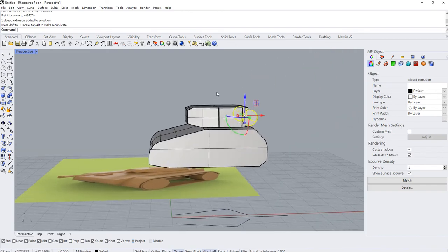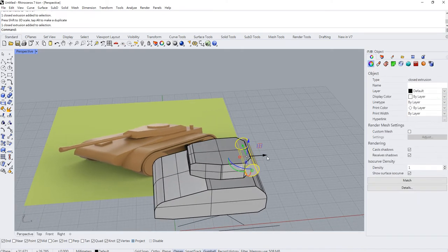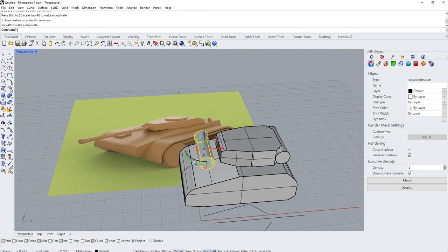It's up to you. So finally, let's create this tube. Let's use this cylinder again, okay? Copy. Hold on your Alt key to use combos for copy. Rotate 90 degrees.